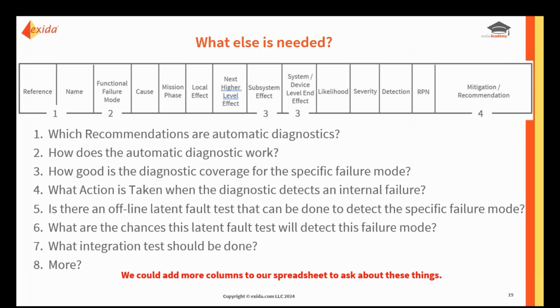So what else do we need? We need to know which of the recommendations are automatic diagnostics, and if they are, how do they work? What's the diagnostic coverage, that is the effectiveness? What does the diagnostic do when it detects an internal failure?